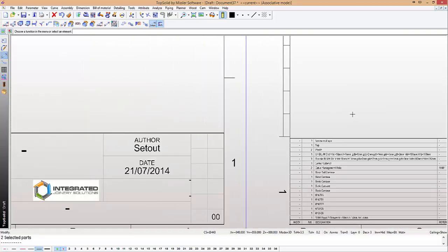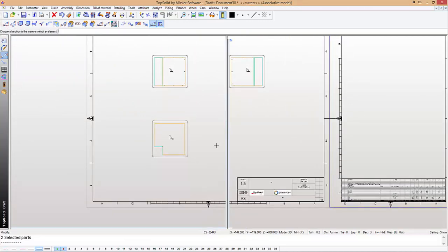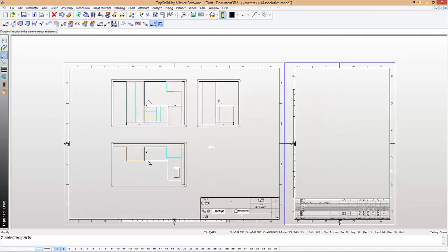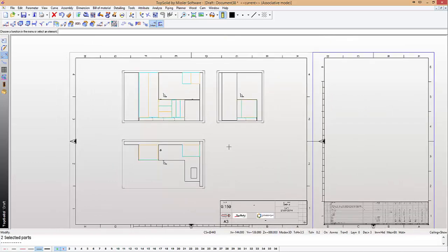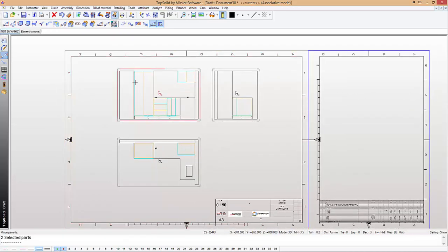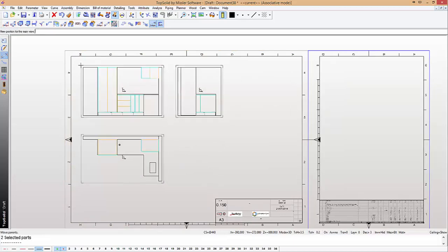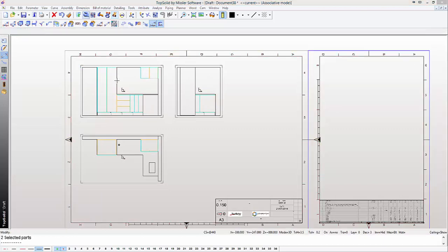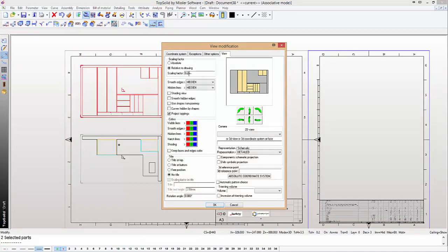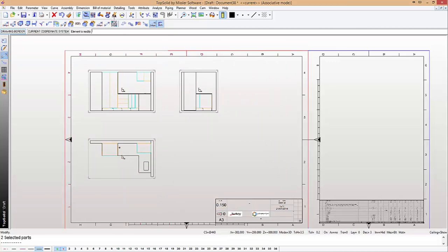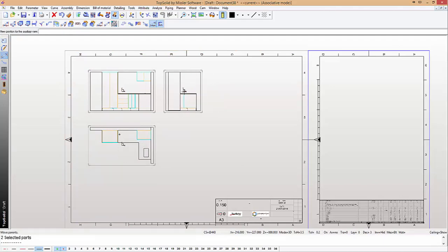Okay, if we just scroll in, you've got various different base carcasses, tall units, you've got your cable management hole and hardware. So if I just go back to our overall kitchen plot page, I can now move these items, of course, to any location within the drawing. These viewports might be just a bit too big, so what I'm going to do is modify them so they're a bit smaller here. Press OK and move them into better location. Perfect.